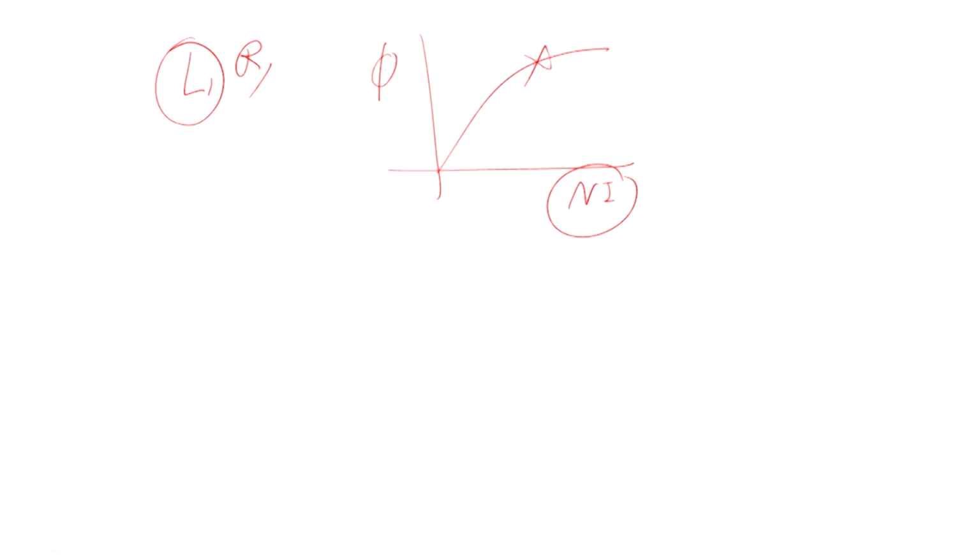For this reason, we require to specify: at no load, the inductance which you will measure, what should be the value? Full load inductance, what should be the value? And generally it can be overloaded, and what should be its value? And accordingly, you will choose the number of turns.